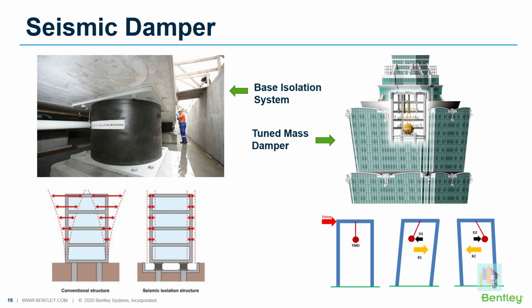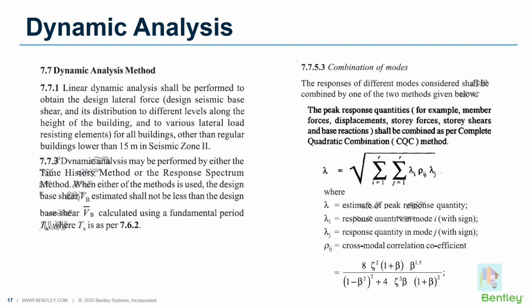Also, it is a challenge for the structural engineer to select and place the lateral load resisting frames, including shear walls, bracing system, outrigger elements properly so that not only the seismic force is distributed properly, but also additional torsion due to static eccentricity is within limit.